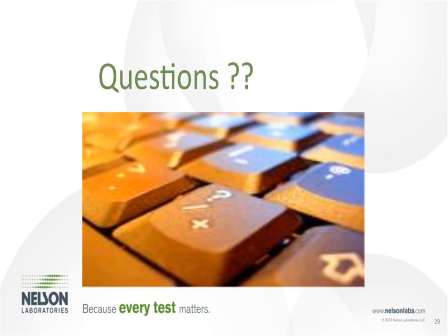Another great question, and the answer is yes, although it is a little bit more difficult to do no testing. But we have done it. You really have to get very detailed information for the material, your history with that material, like it's from the same supplier, nothing's changed, the processing you're going through is exactly the same, you look at how it's used, all those endpoints, and if you can really talk to that, then yes, we can just do a paper approach, and that's been successful for those kinds of circumstances.